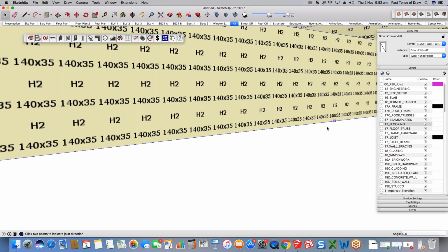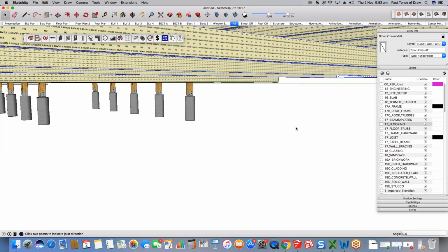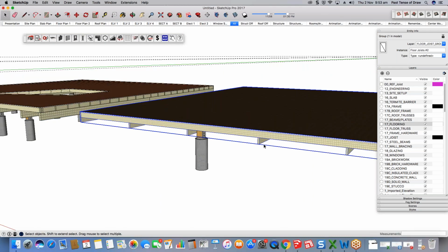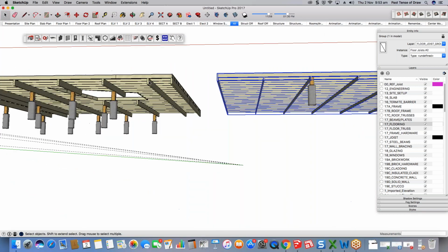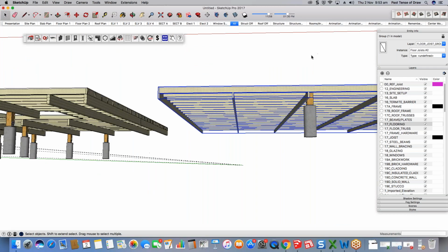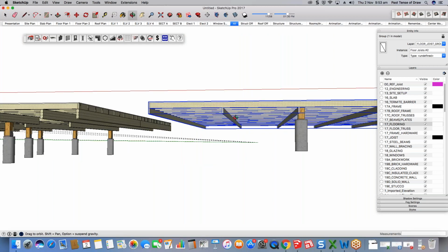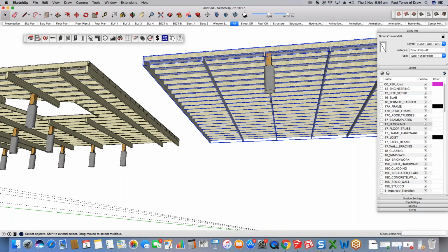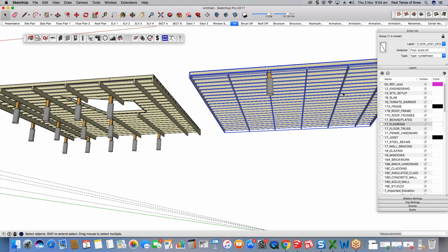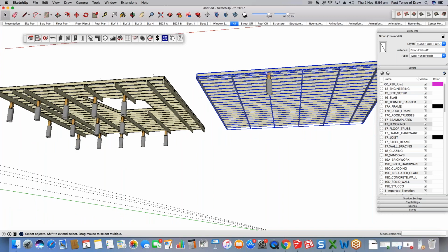So again, it might be more beneficial that you don't create or generate the bearers or girders inside of the PlusSpec tool, and instead you're using the beam tool, like I showed you over here, to put in those bearers and girders in the position that you need them. So if you do update your overall joist, the bearer section, so the beam flush, will remain where it is. I hope you all understand that. Essentially, going back into the beam tool and just drawing it in, making the array, it's in the position you need it, therefore it's fine.